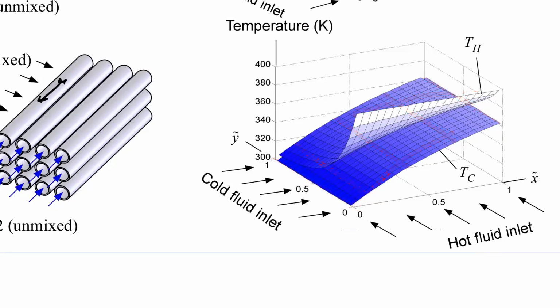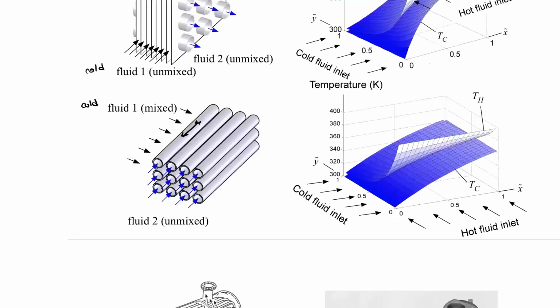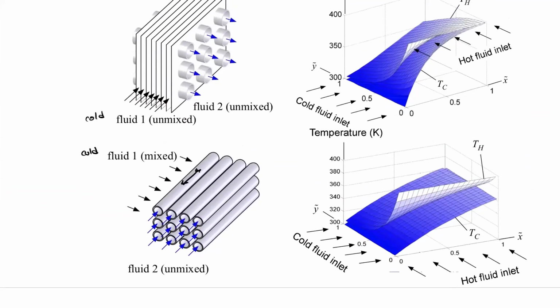So it's a slightly different solution. It's not the same degree of difference from this to, say, parallel or counterflow, but it is an important distinction, and it can lead to a different solution. So when you're using those cross-flow heat exchanger correlations, you're going to want to keep in mind: is my fluid mixed? Is it unmixed? Often it's actually somewhere in between. So you have maybe a mixed situation, but you don't assume that there's perfect mixing. So you might use the mixed correlation to get you a bound on the system, but it's not actually the perfect solution.